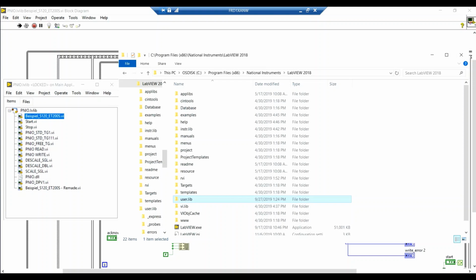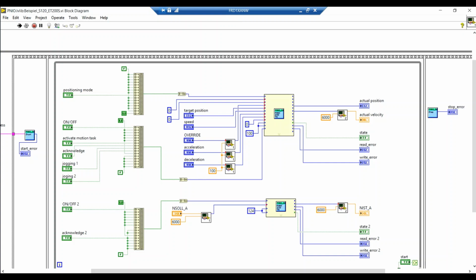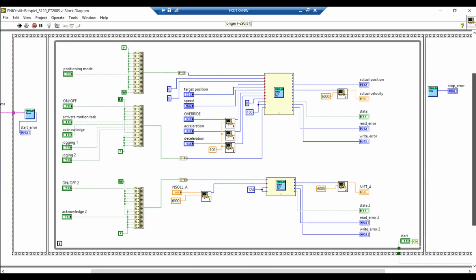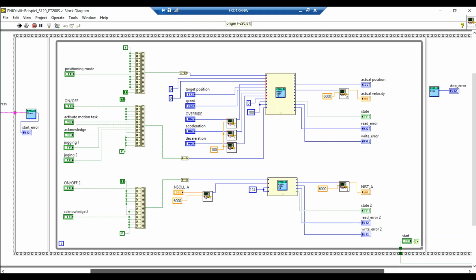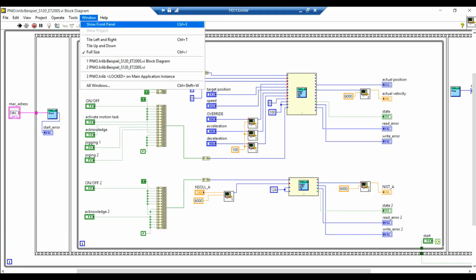Using the LabVIEW application, the structure of the application example is explained in this section, and you are shown how to operate the LabVIEW user interface. As shown in the diagram, the user interface comprises three components. The first component is used to operate the PROFINET controller. The second component is used to operate the basic positioner via direct setpoint input (MDI), the upper axis of the S120 demonstration case. The third component is used to operate the speed-controlled axis, the lower axis of the S120 demonstration case.